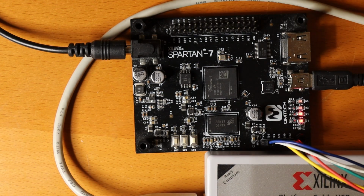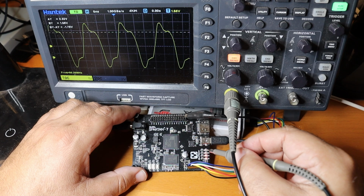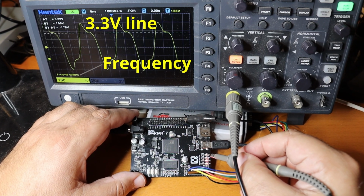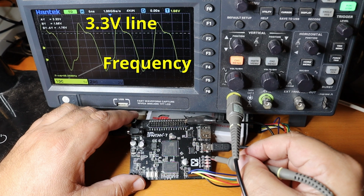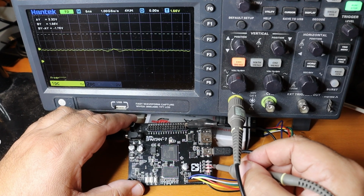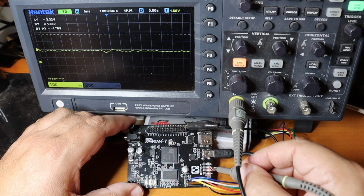While they seem to be in the same state, they are not. If we look at D3, which is the LED we programmed, with an oscilloscope, we can see a 50 MHz 3.3 volt wave on it. It doesn't look very squarish, but that's how things look in the real world. On D2, we see no such wave. It's at a constant voltage.